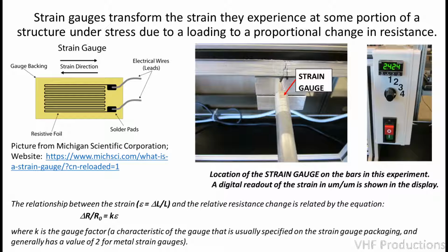As you may recall from a previous lab, where we determined elastic modulus using wave speed measurements, I explained how difficult it is to measure strain, particularly elastic strains, where the physical displacements are very small. To measure strains in this lab, we will employ the use of a strain gauge, a small electrical resistor, typically in the form of a copper wire on a substrate, and the copper wire has a very long length in a very small area.